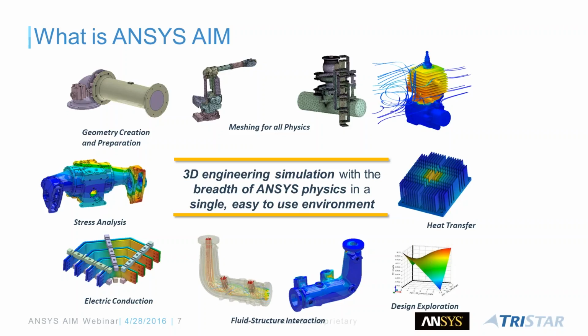It still has the breadth of ANSYS physics that we all know of, but in a single, immersive environment. It has a lot of process templates, guided workflows, etc. All the way from importing the geometry, creating the mesh, and then depending on the physics that you would like to simulate, it could be structural mainly, or fluid, or both, fluid structure interaction. So it also supports multiphysics.